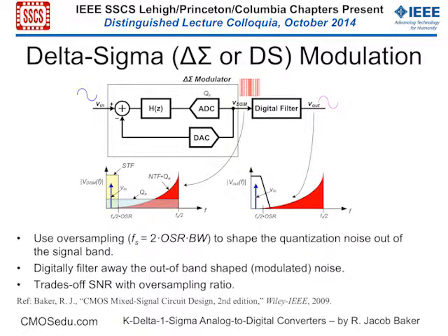You have your signal coming in. I just gave the example of the DC water going into a bucket. Here's your bucket, and here's me standing there looking into the bucket. Then I'm going to take my cup, which is this DAC, which I have to fill precisely, because if I'm sloppy, I don't fill it precisely. So that is the one thing that is precise. That's why we use 1 bit, because it's either full or empty, perfectly linear. I'm going to subtract or remove that cup of water from the bucket.